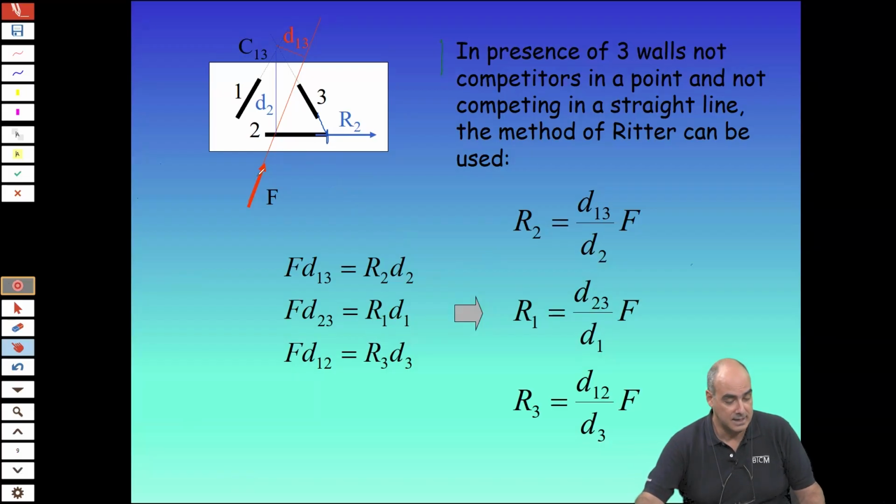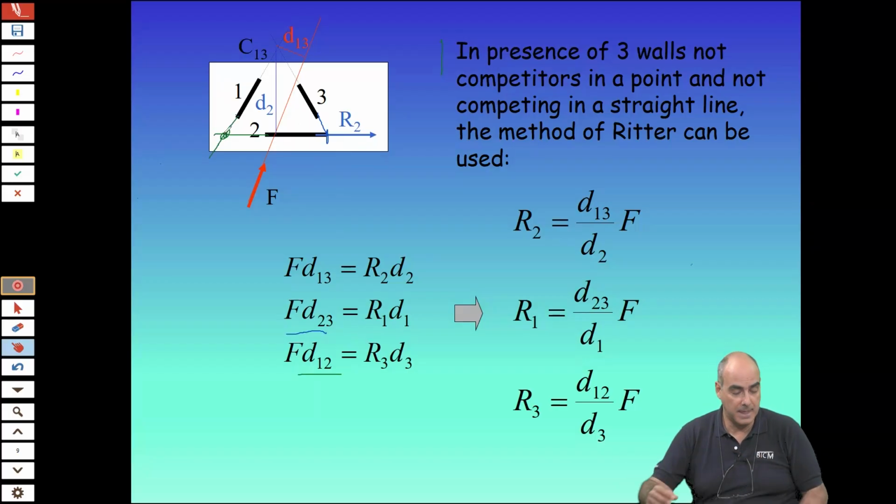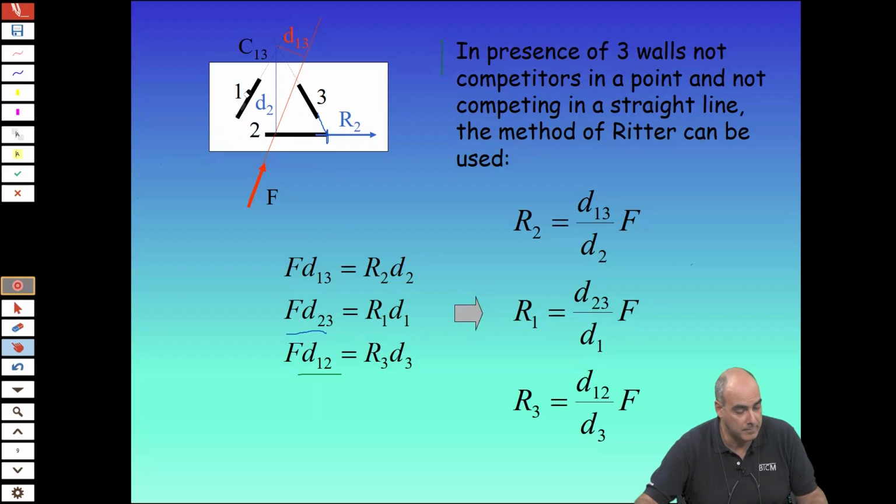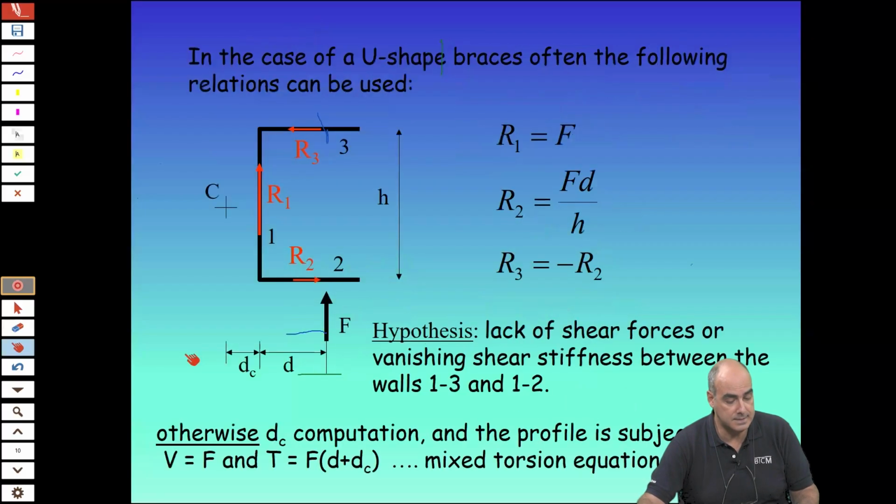So you have just the contribution of the force, in this case this one, times the reaction force of wall one. Let's change the color. When you write about this point, which is 1, 2, the force in wall one and the force in wall two disappear because they converge into that point. So you can, in a very simple way, work out the forces in the system.